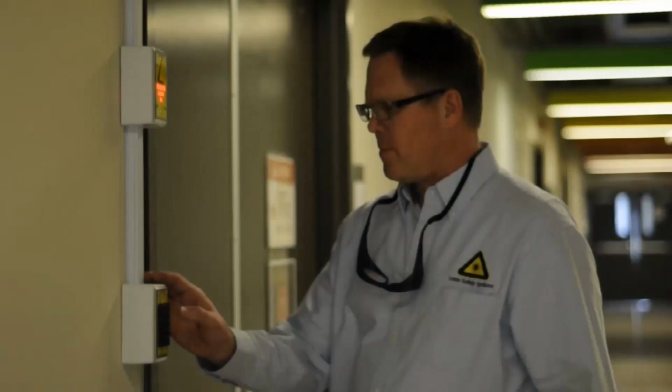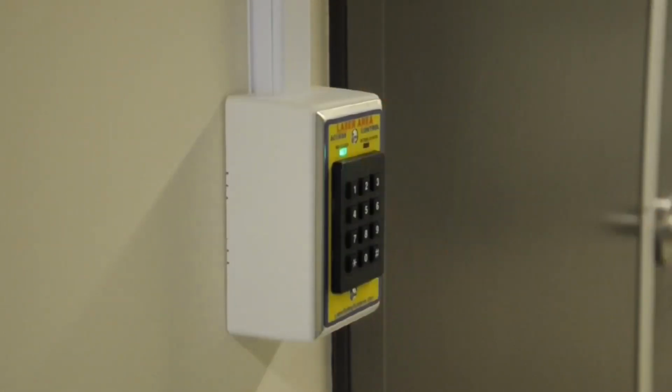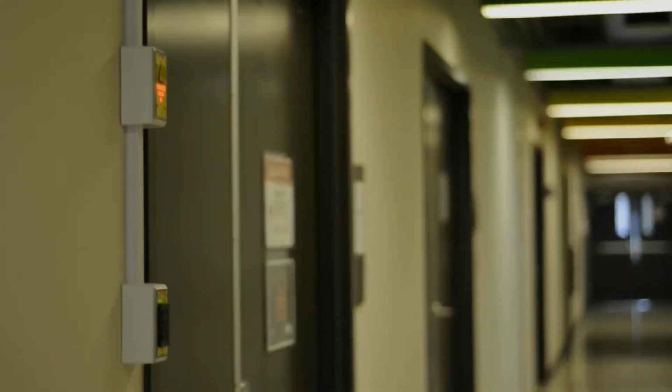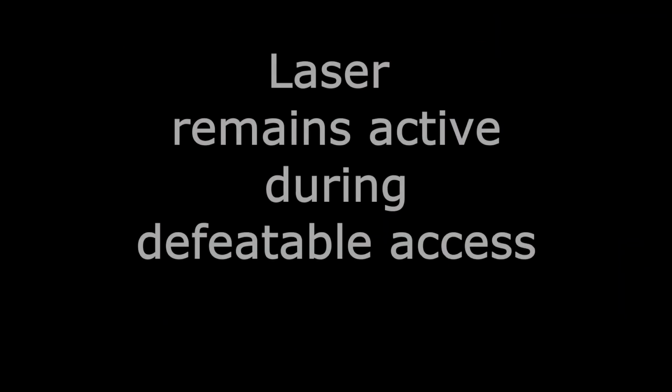In some installations, a facility will link our 2388 main controller to their card reader systems, and the keypad is not required. We wish to stress here that the laser is not disarmed in any way during these access routines. If there is a potential for laser light in excess of the maximum permissible exposure to leak through the door, you must have a laser curtain or labyrinth installed behind the door to prevent exposure.